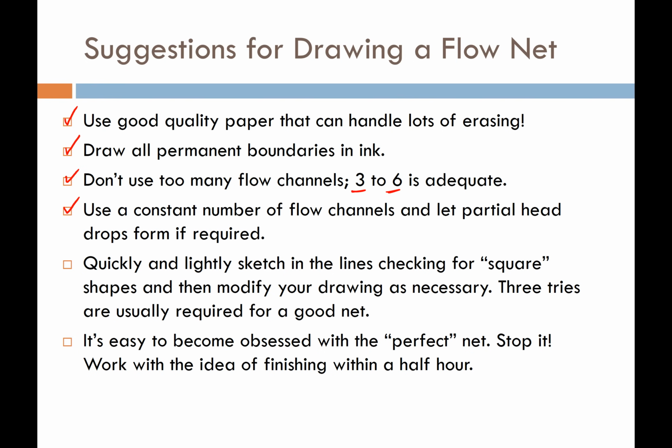I recommend that you use a constant number of flow channels, and so don't do any partial flow channels. Instead, if you need to do anything that's partial, go ahead and draw partial equipotential lines or partial head drops as necessary. But for the most part, you really don't need to worry about that too much.